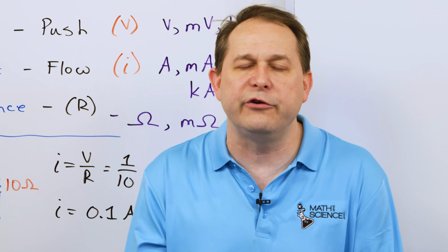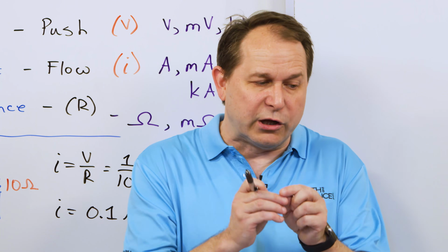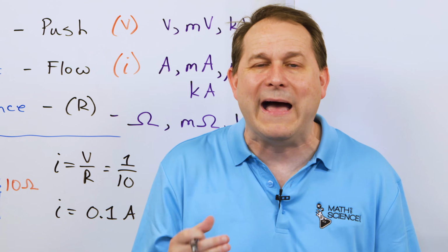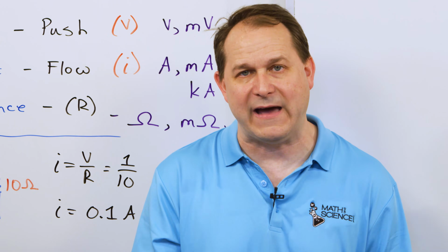I wanted to use a large one because I don't want to burn up my resistors teaching you these concepts. But the larger the resistance, the larger physically the resistor is, in general, the more power that it can take, the more heat it can dissipate without burning itself out.